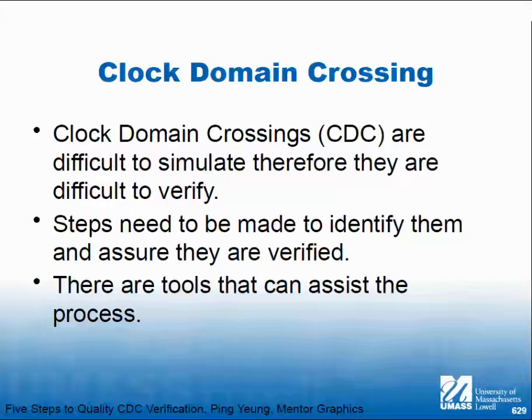Now, the reality is if I put that inverter in the lab, first of all, it's not going to measure either of those two values because those are temperature sensitive and process sensitive, voltage sensitive, but it's going to be an actual value. And it's not going to be discretely measured at those picosecond levels unless I have an oscilloscope that's a discrete time device.